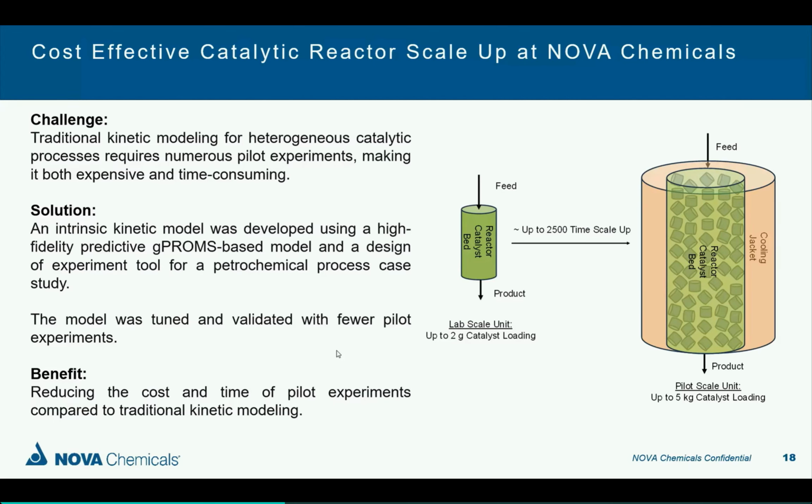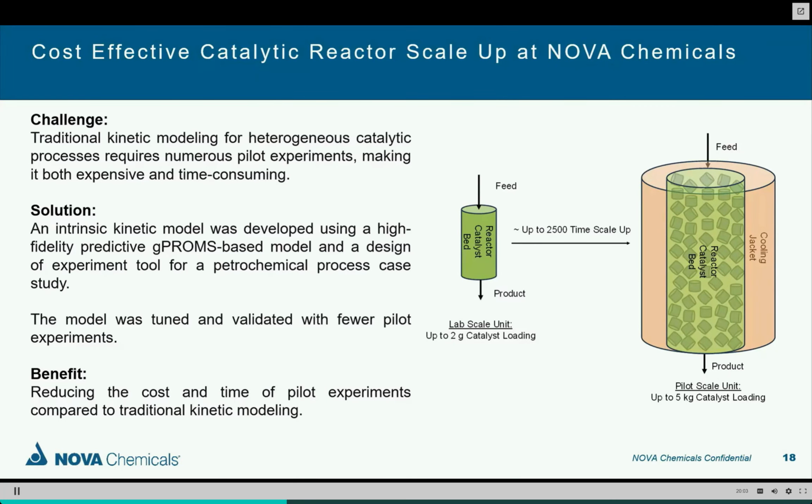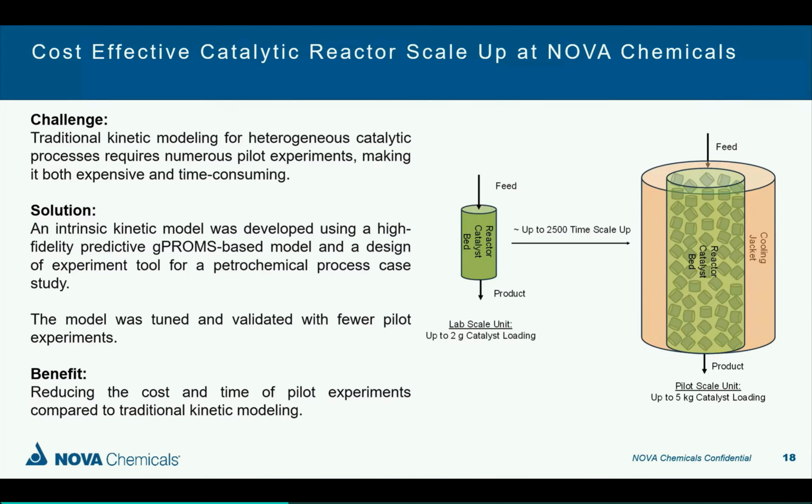Now, following that, using the design of experiment at the pilot scale, which, as you can see in the screenshot, the scale-up factor was up to 2,500 times. Catalyst bed correction factors for transfer and hydraulic phenomena were developed. This resulted in development of the kinetic package, which consisted of intrinsic kinetic model plus the catalyst bed correction factors. Now, using the kinetic package, subsequently, the kinetic model package was capable of predicting the performance at the pilot scale.